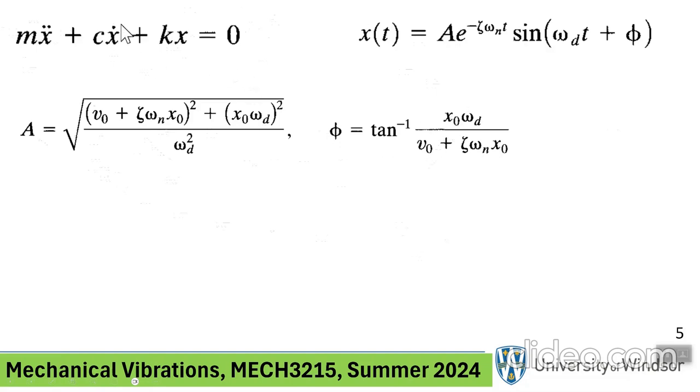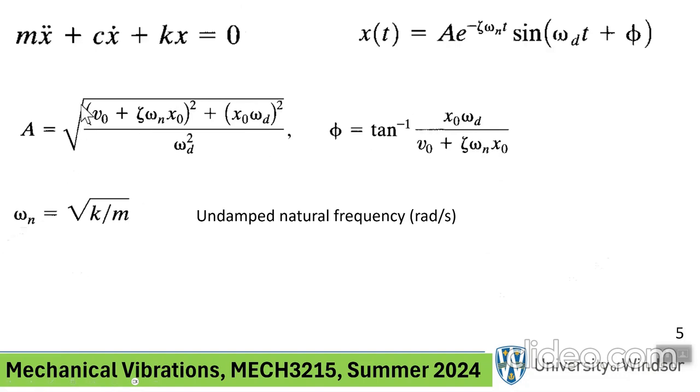So when there is no damping, this term zeta is 0, and you can just cross this out. This 0 times that, you can cross it out, and same thing down here. In that situation, omega d is omega n. So if you leave out anything that has zeta here, this term and that term, and replace every omega d with omega n, you get exactly what we got in lecture 2. Okay? That's what we had for omega n, the natural frequency of the vibration.